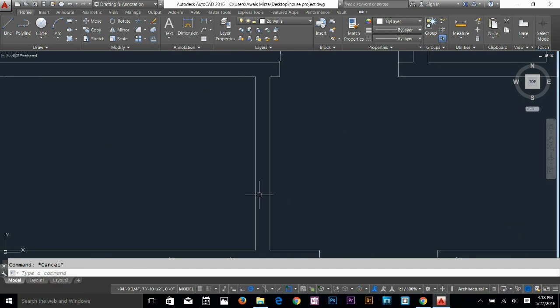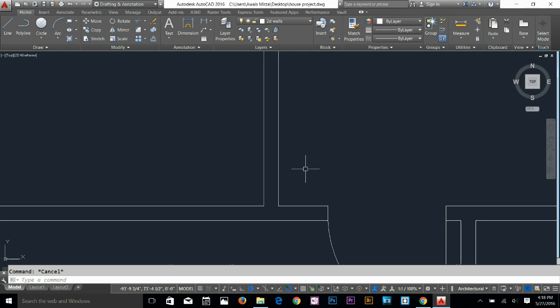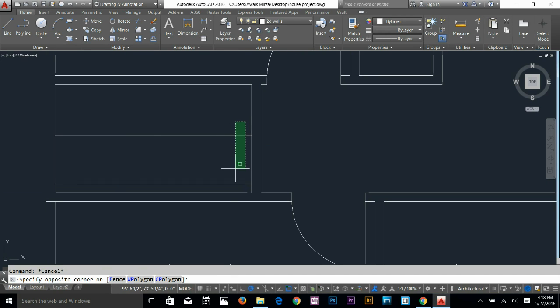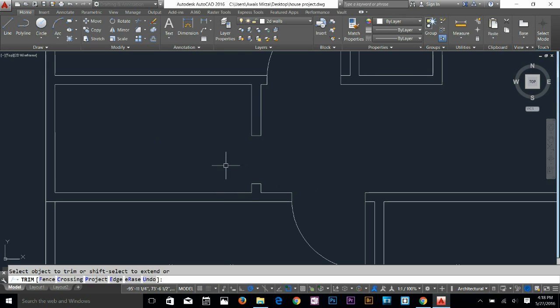That's done. The bathroom door is going to be a bit smaller, 2 feet, so offset 4.5 inch, offset, let's say 2 feet is fine, and then use both vertices, select that vertex. Okay, hold down shift key, select that vertex, and then select that again. You can do that at the same time. So TR for trim command, done. Polyline, go about 2 feet, come up 1 inch, A for arc, and there you go, done.